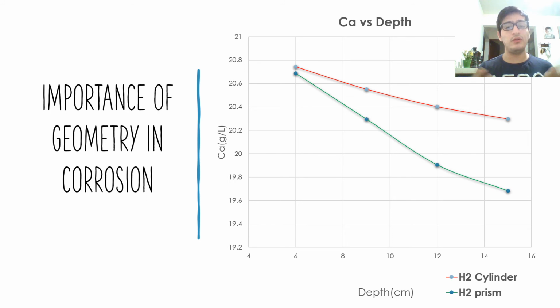So we now know which mixture is the best, but we also need to identify which geometry is the best. By comparing both concentration profiles, we can see that the rectangular prism has an even lower diffusivity in comparison with the cylindrical one. This may be because the surface of the cylinder is equally apart from the center at any point of the surface, while in the rectangular prism you have edges, so the distance will vary as you get farther away from the center. This will cause the concentration to take longer to reach the center of the pillar.